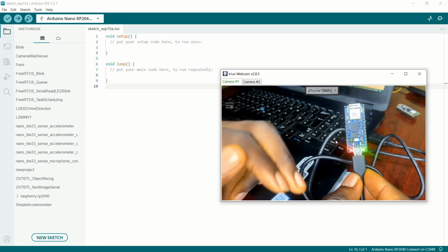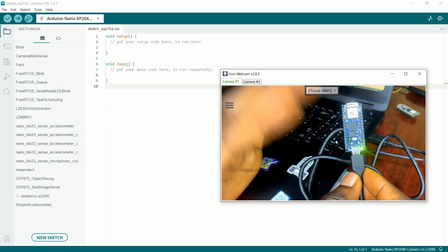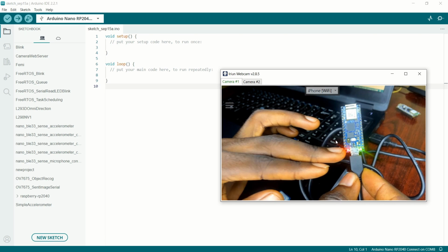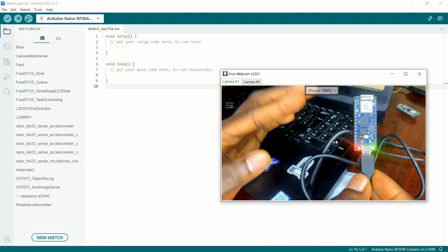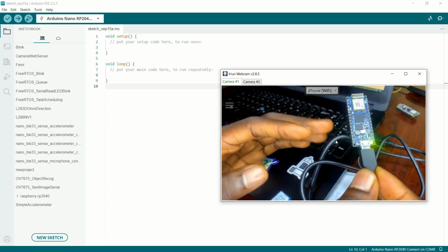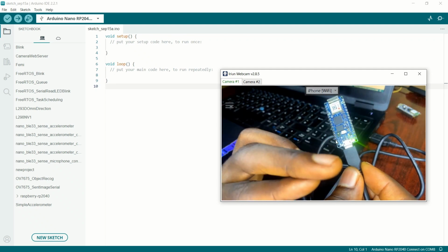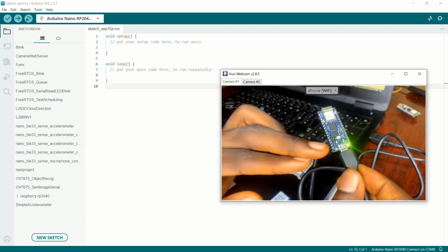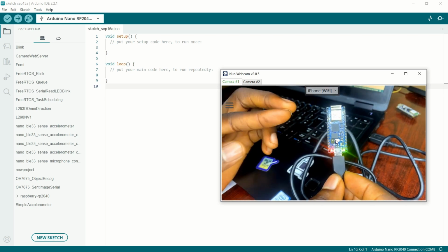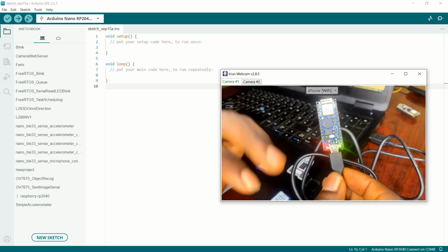So this might not really be a problem. If you want to control the RGB, you have to maybe write another code to control that. But the Blink example just controls the built-in LED that is attached to pin 13. That's most times what you want to happen. That's most times the actual performance you're expected to see. So once you have that uploaded, you can see that the onboard LED is blinking, and that's how you can program the Arduino using the Arduino IDE directly. This will most times be the way you're going to program the Arduino board.